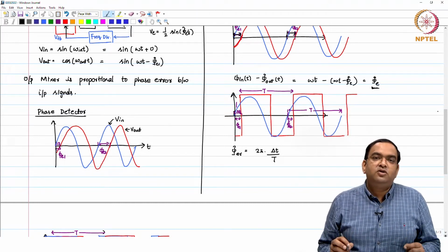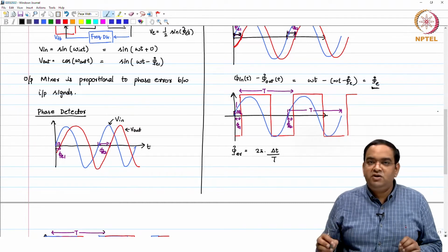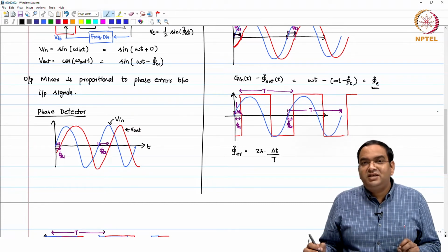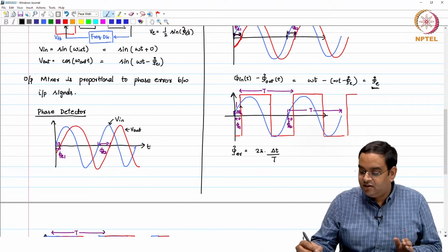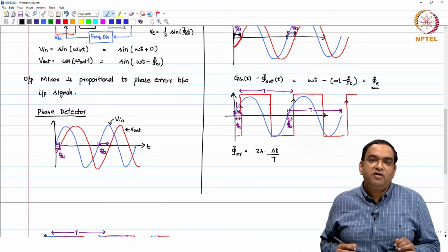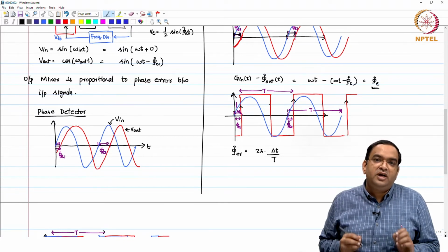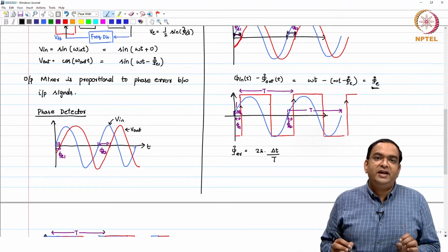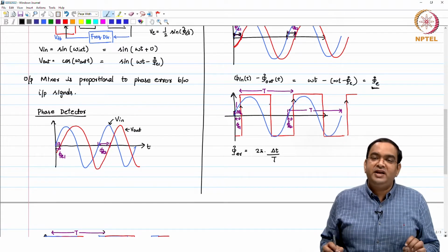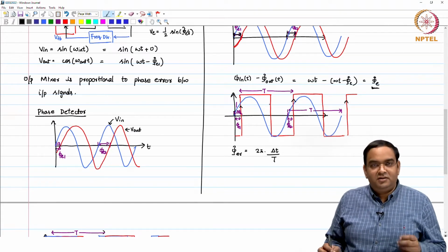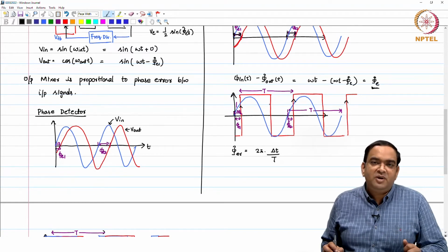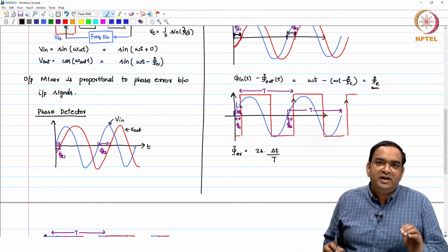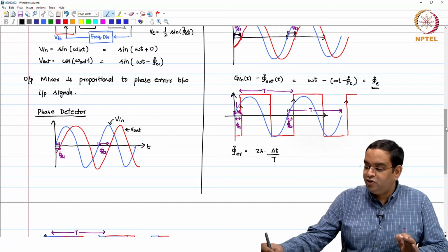What we need to do in the PLL block is generate an output clock in such a way that the rising edge or the period of this output waveform does not vary. Ideally, that should not vary at all. Okay. In real PLLs, it will vary by some amount, and you would like to keep that variation limited. Okay. So, that is what we need to do.